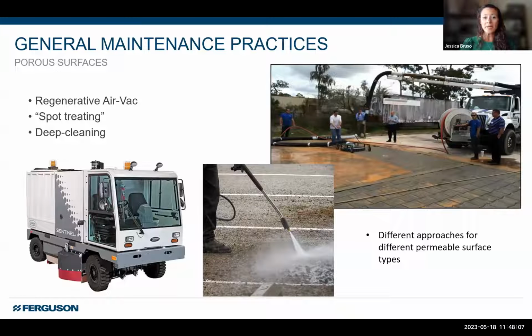But you can do some pressure washing. It's really important to make sure you have the right distance away and the right angle to make sure you're pushing things up and out and also preserving that surface, especially if this is going to be more of a pervious asphalt or concrete that could be a bit more disturbed than just the joints, or the blocks in general, I should say.